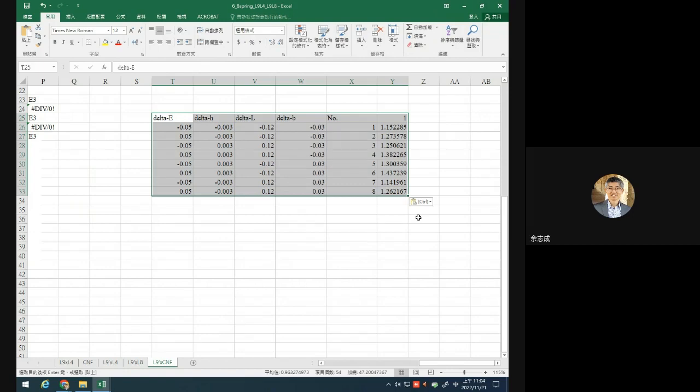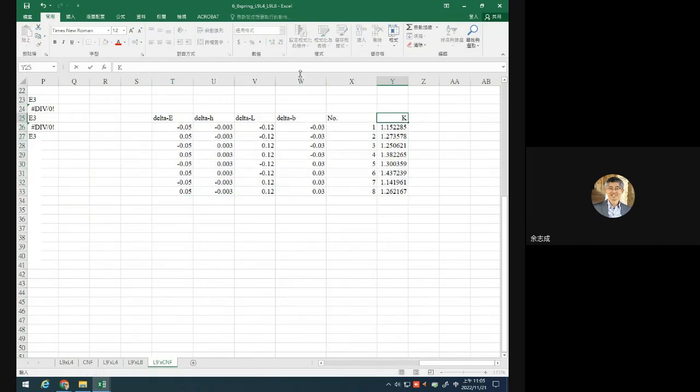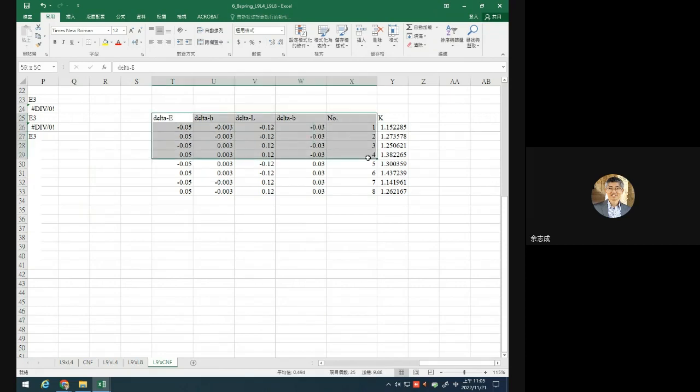Then you can copy the first set of outer array experiment to here, and it will look exactly like an orthogonal experiment for the noise factor. And this is the output due to design number 1 under the influence of these 8 noise factors, L8. See? Right? So let's copy that over.